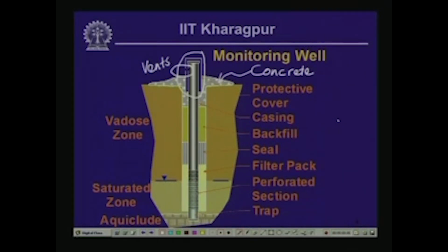Typically you can use silty clay or clay silt or glacial till or that kind of material which is not totally permeable, and underneath the backfill there is a seal. This seal is constructed using very fine grained material such as bentonite in order to seal the portion of the casing tube that is actually used in extracting groundwater, which is in turn encased within a filter pack.